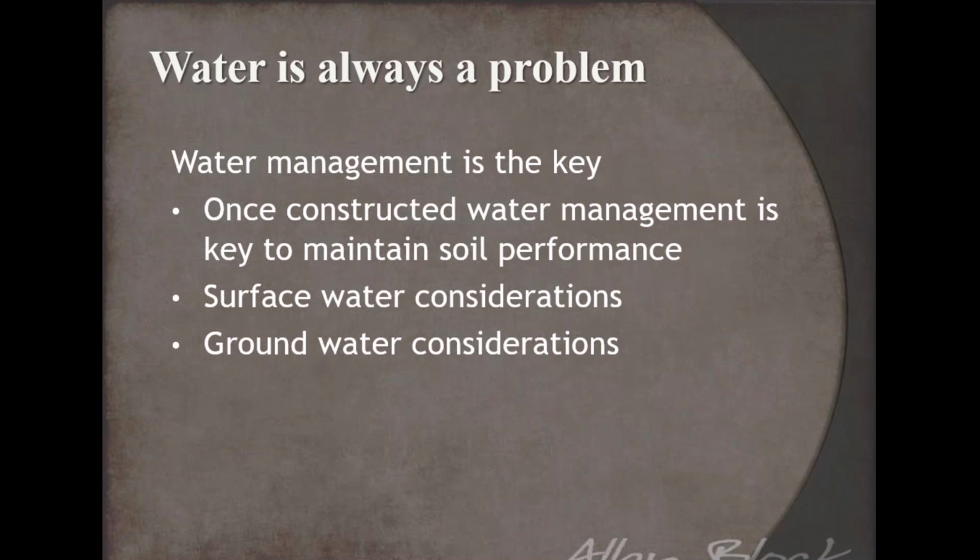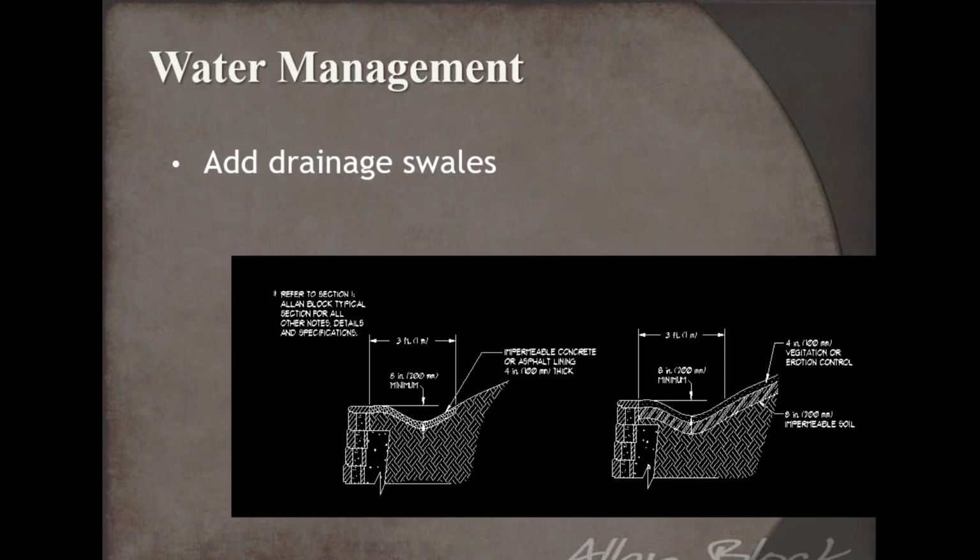And so it gets down to two sources. We've got the surface water, we've got the groundwater. Surface water to me is the obvious one, but even the one that is probably neglected the most. On residential applications, a lot of the culprit is the downspouts. Where is that water being dumped? And if it's going right behind the wall, now that's going to change your soil characteristics. You're introducing additional water, and now you're past your density curve, your compaction curve already. So we're looking at berms, swales, getting that water out and around so it doesn't even have a chance to hit the back of the block and start saturating those soils. So this is where you need to be proactive, making sure these surface water potential sources are handled.